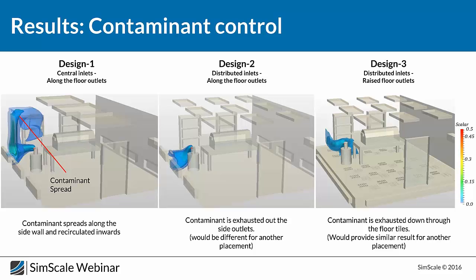But the good thing about this design is that wherever you place the source of contamination, the results are virtually the same. You could expect, if you put it in the middle of the room, move it around, if the source is not something that is fixed, is something that moves inside the room, it's not going to change the results. And at the same time, it means that when you're designing the room, you do not have to necessarily design the interior of it at that time.